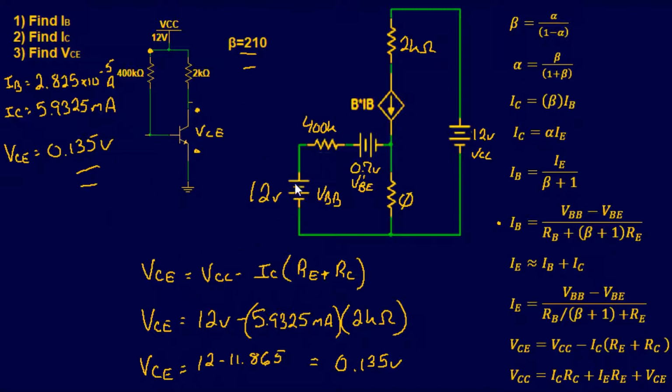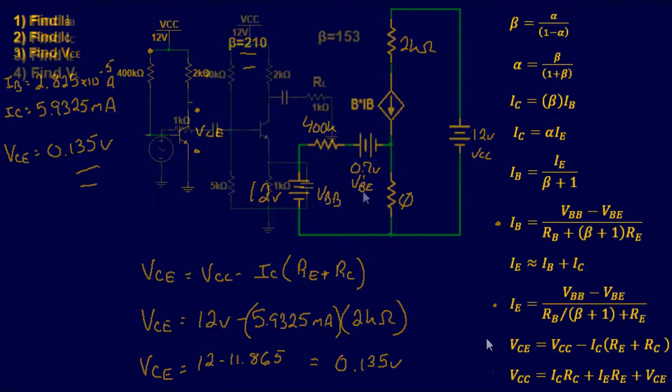However, it's just going through it and understanding how we're getting these. Now again, think about this guy right here as a diode, hence why you have a 0.7 volt drop, and that's why you have to use it in your equations here. And these two equations right here are going to be your bread and butter as far as finding some of your answers. It may not be in some of your textbooks, but I'm providing it to you so you can move along quickly. Let's do one more example so we can get a little more experience with BJTs.